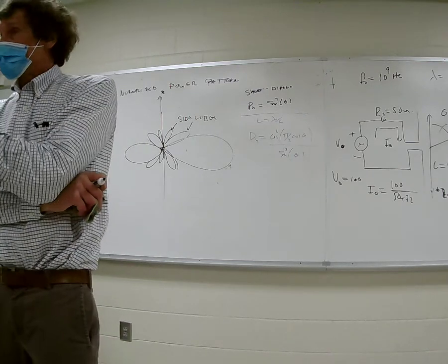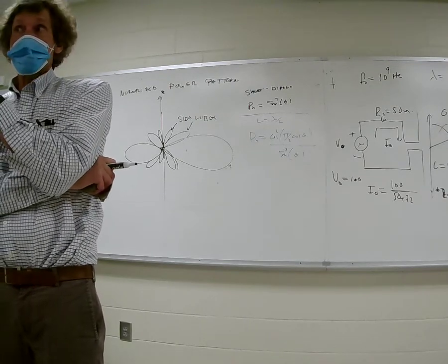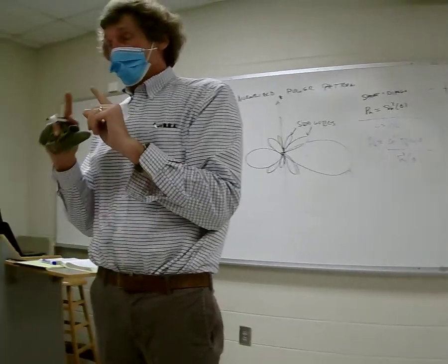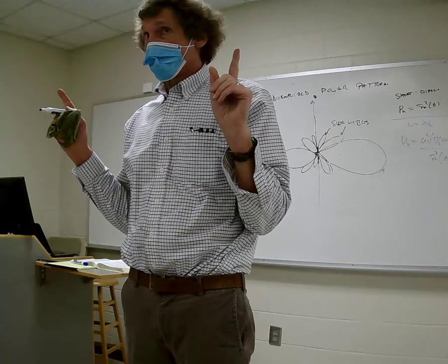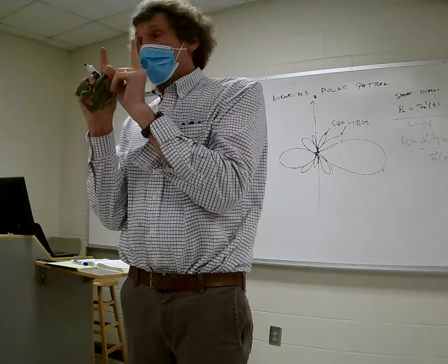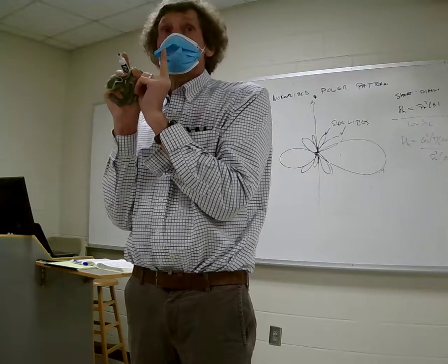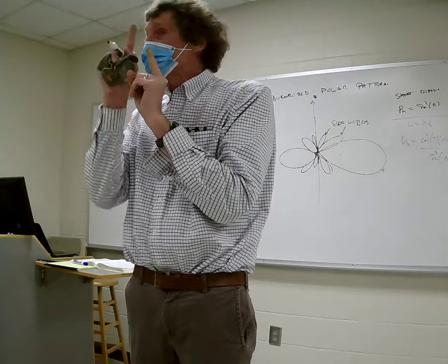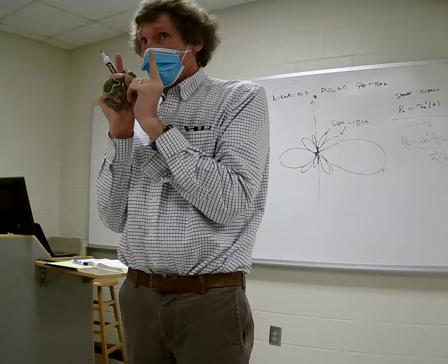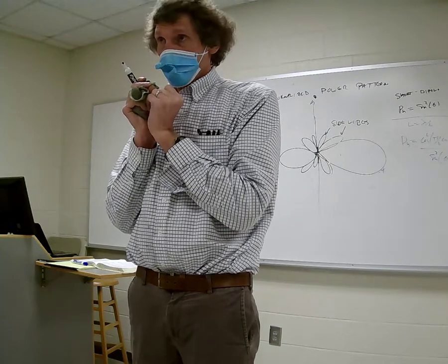I do not expect you to memorize this. However, for normal incidence, you should know that the reflection coefficient is the impedance you're going into minus the impedance you came from, divided by the sum of the impedance you came from plus the impedance you're going to. Are y'all with me on this? If I give you something with a shield, a certain thickness, and I ask how much is transmitted, you can assume it's thick so you don't have that multiple bounce pattern. You with me? You should be able to do that, okay? If I ask you for skin depth, you should be able to do that.